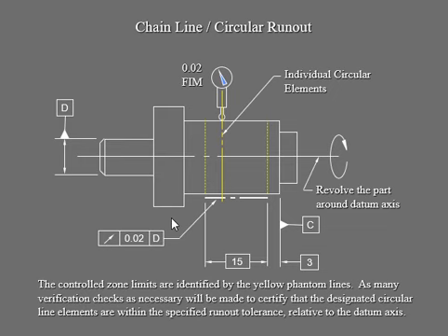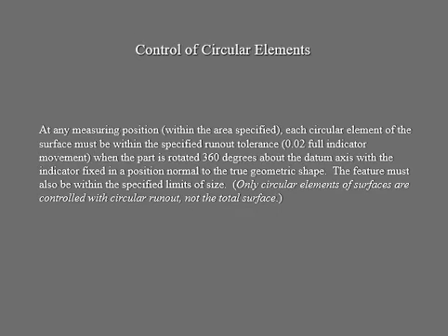Again, your Runout tolerance is completely relative to this axis, which is your rotational axis, because the part is going to revolve around that datum axis when we probe.